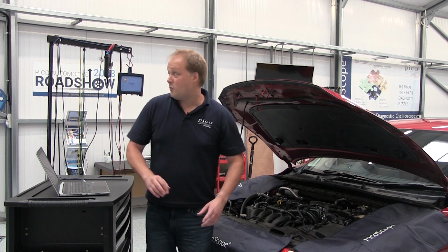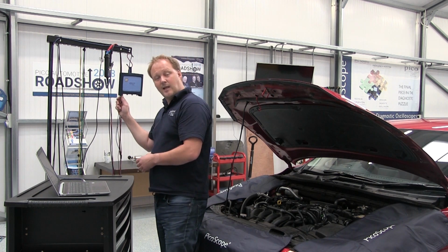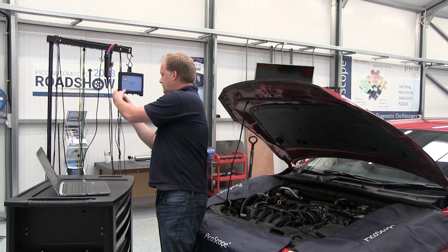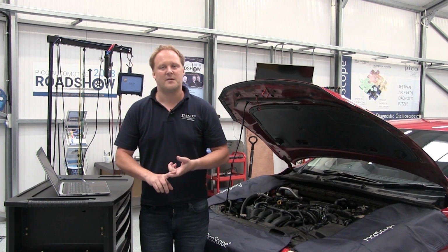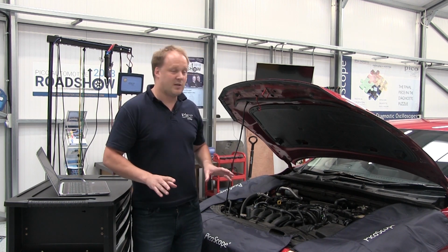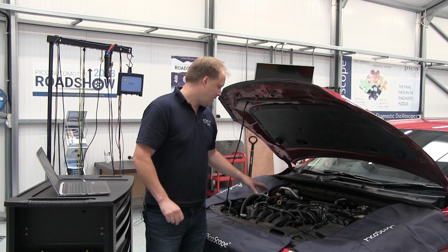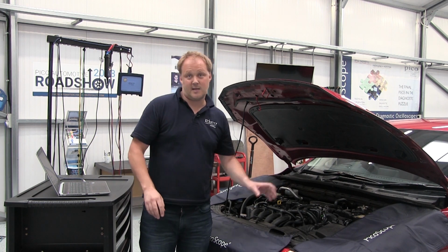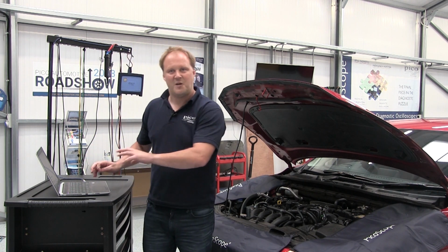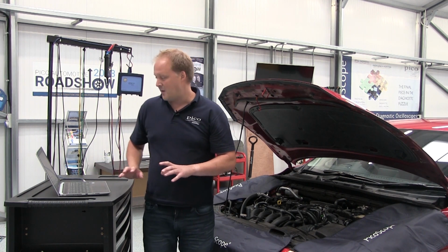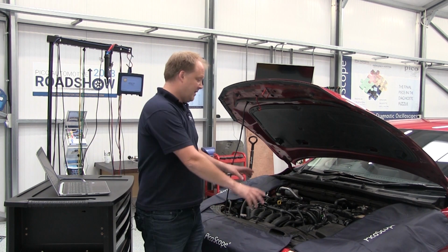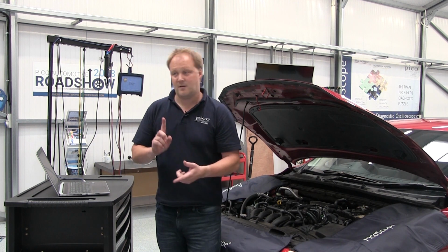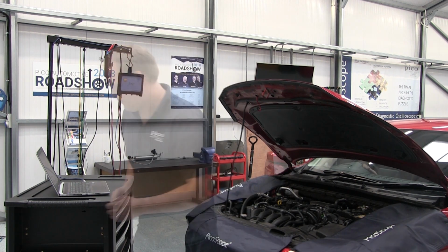So we're connected to the vehicle, we're connected to channel A on the PicoScope. Now all we need to do is run the test. So to do this, we want to capture a running waveform from the engine. So we start the engine, start PicoScope. Once we're happy or not with what we've got, then we stop PicoScope and then stop the engine. So first thing, let's start the engine.